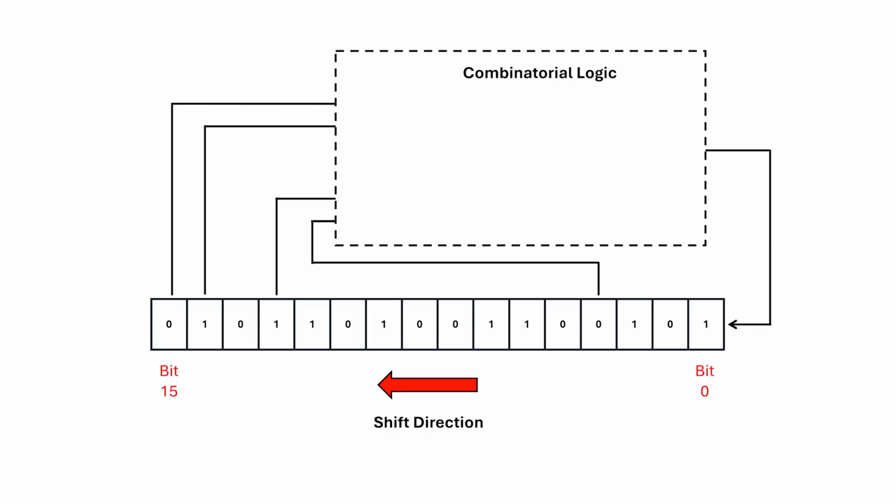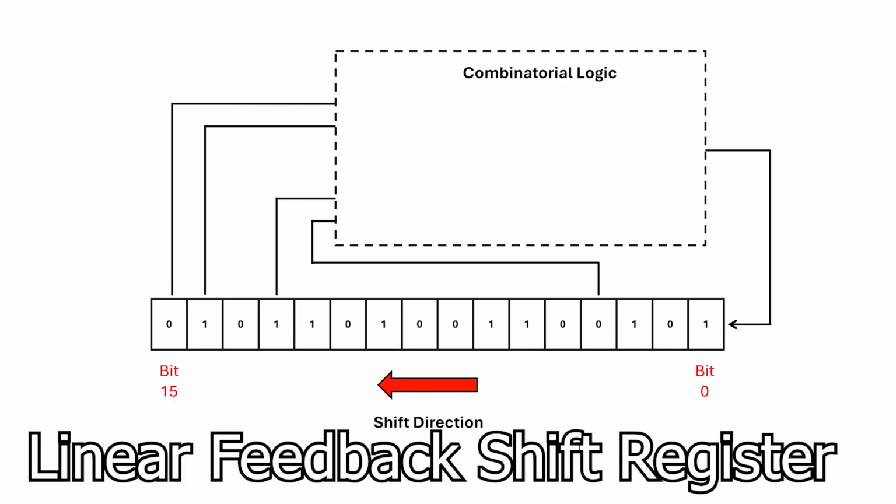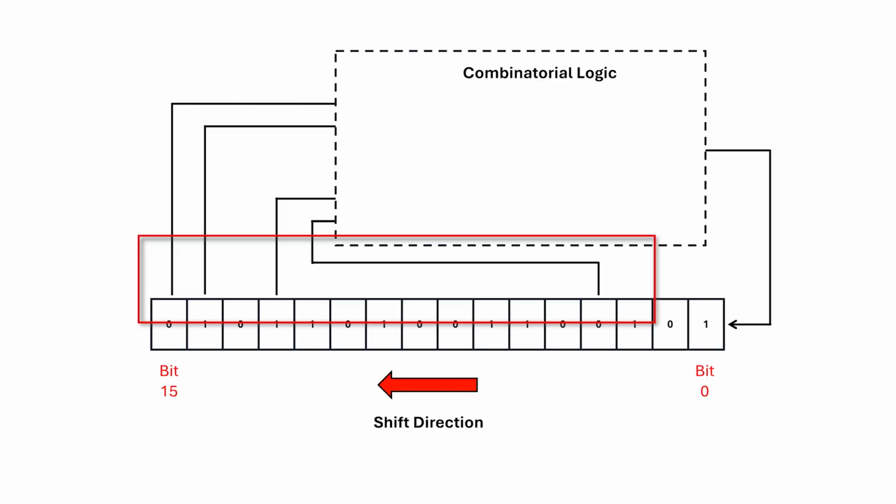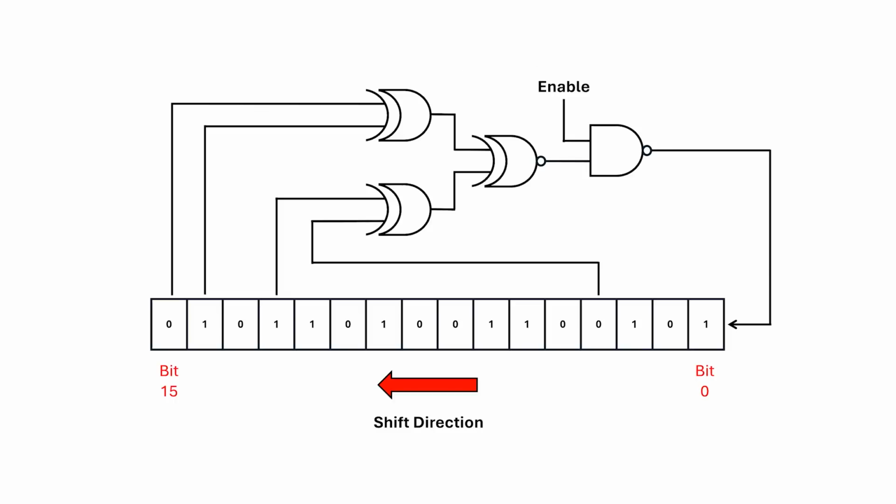The VIC-20 itself actually uses a simpler form of pseudo-random number generator, which is good for generating one bit at a time. It's called a linear feedback shift register. It taps off various bits to figure out a new least significant bit, then it shifts the value in the register left and inserts the new least significant bit. Again, this is a form of a finite state machine. Ideally, we want this combinatorial logic that calculates the next bit to contain at least a few exclusive OR gates, so that on average, we'll produce an equal number of zeros and ones over time.